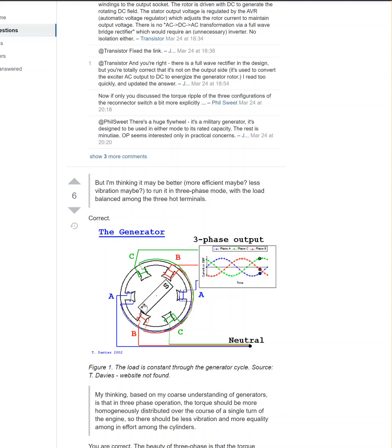So if you look at here, that's phase A, phase B, and phase C. Okay, so look at this. When the North Pole reaches A here, that's the voltage generated in the A coil, and when the North Pole reaches B, that's where the red line is going to start producing the voltage. I mean, how come we have lines here?